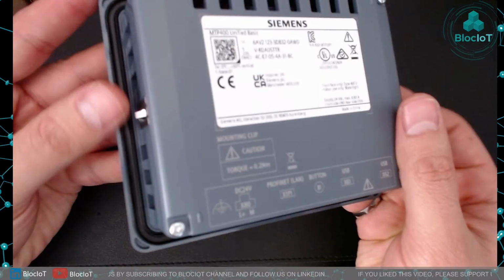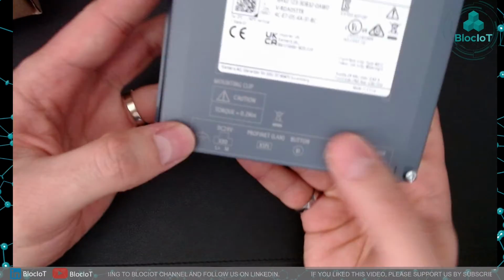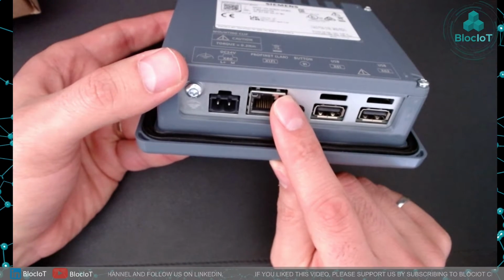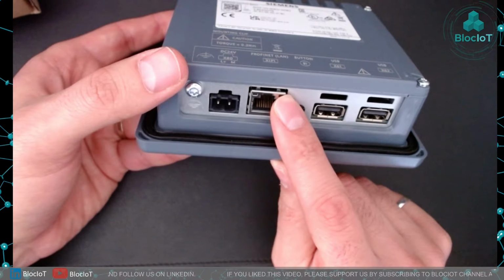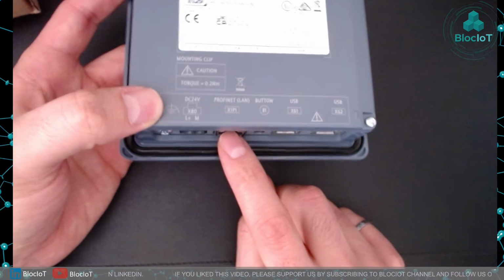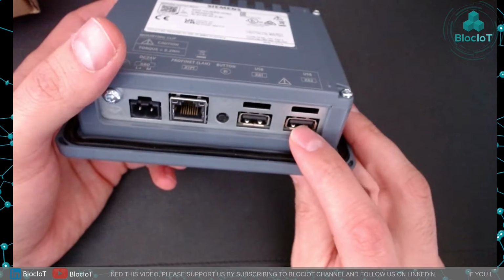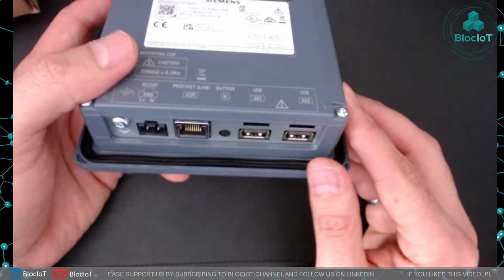And as you can see here on the bottom, you have the power connector, that's just for connecting the DC 24 volt. This device, or Unified Basic panel, has only one Ethernet port compared to the Unified Comfort panel that has 2 isolated Ethernet ports to connect to 2 different networks for different purposes. You can just use it for connecting to the internet, or of course connecting to your OT network for PLC and so on. You get 2 USBs for connecting your USB flash drives for logging data or offline transfer of your project and so on.